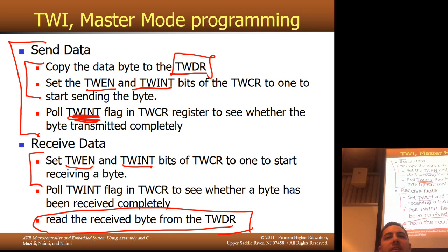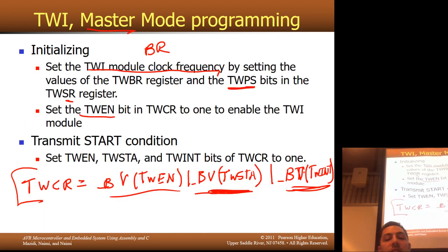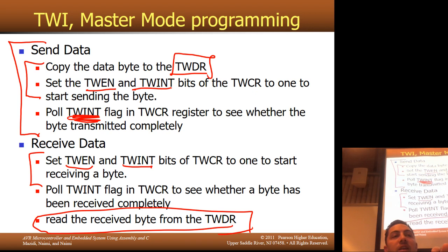Yeah, and that's why it's kind of difficult to write an interrupt-driven routine. Arduino has actually done it. They have a very nice I2C library. They call it the wire library. I don't know why they didn't call it the two-wire interface library, but they didn't. Because of the slave address plus the read-or-write bit, the TWI interface keeps track of that. It knows that you sent out a write address packet, so it's going to take the data out of the data register and send it serially. If you put a read bit into the address packet, it knows that it's going to be sampling the data line.